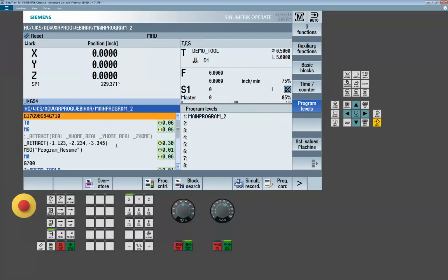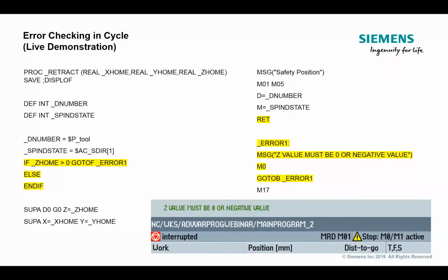So we can start adding conditional checks and traps to keep somebody from plugging in wrong numbers now, just by kind of bouncing around with go-to statements and catching a loop. Now, I wouldn't put it into that indefinite loop and not give the guy a message, because that'll just drive you crazy, right? You're not going to know what's going on. So just keep that in mind as you start to build some of this stuff, that you want to give as much interface to the user as possible. And you see any message command gets displayed right up top. You know, we've talked about these message commands in the past, but it's just MSG, parentheses, and whatever's inside of quotes will display on the screen.